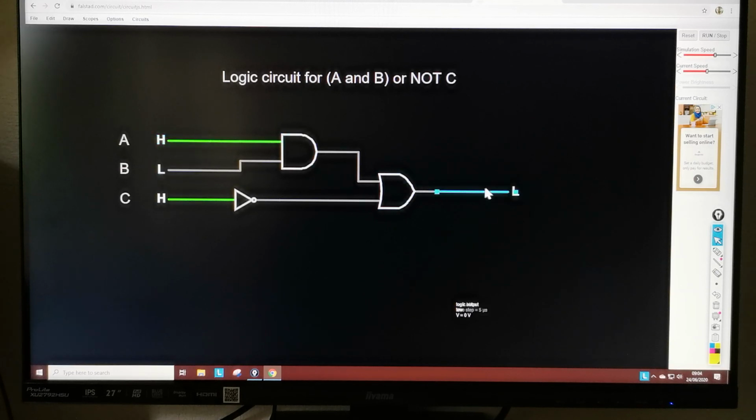And you can see some combinations will bring the output on, others not, and that should follow the results from your truth table. So the top line in the truth table, remember, is 0, 0, 0. So to simulate that, we put in low, low, low, and we should find that on the truth table, the output is a 1 for 0, 0, 0. And we can use this tool to check all of the outputs in the truth table. And as long as the circuit coincides with the truth table, we know that it's built properly.